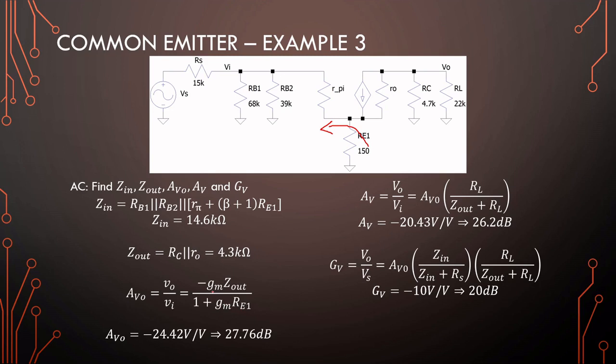Okay, so that brings about that we are not dependent on temperature anymore, and Z out over RE1 gives us the choice of our gain. But please use this equation if you don't want to make rough assumptions, because you need to test that assumption later on.